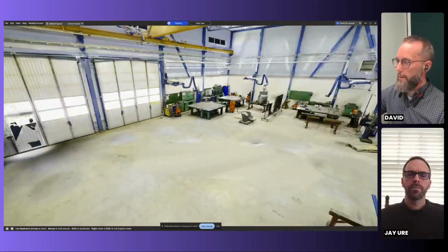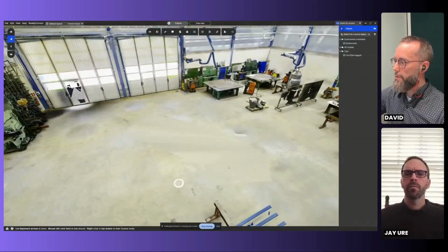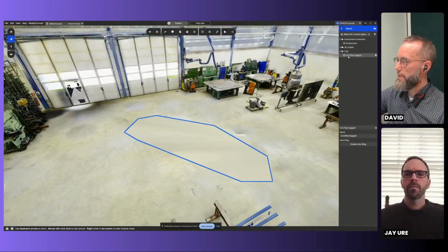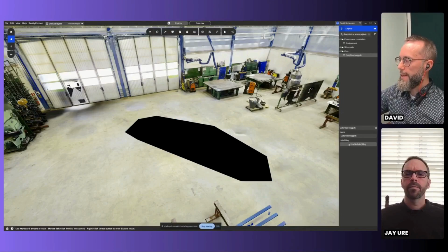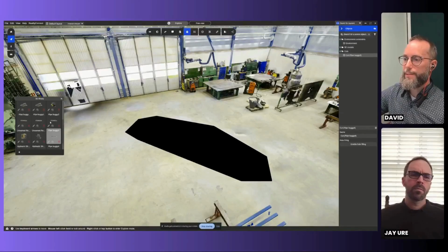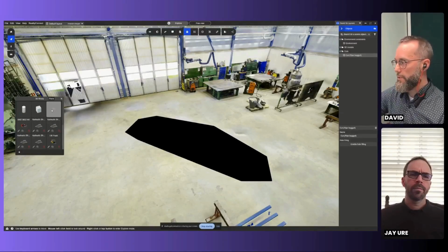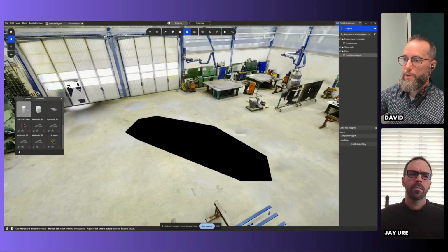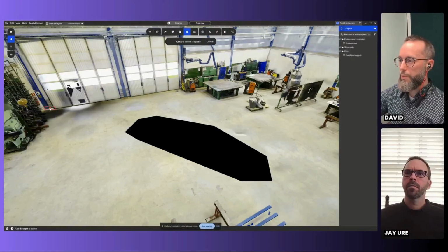Now, you can see the cut on the floor has been filled using the hole filling option. You can always disable that. And for, let's say, more complicated surfaces, you could use the plane primitive instead of using the automatic filling option. So again, the primitives are those 3 shapes that you can find here at the top of the 3D library. I'm going to use the plane one.